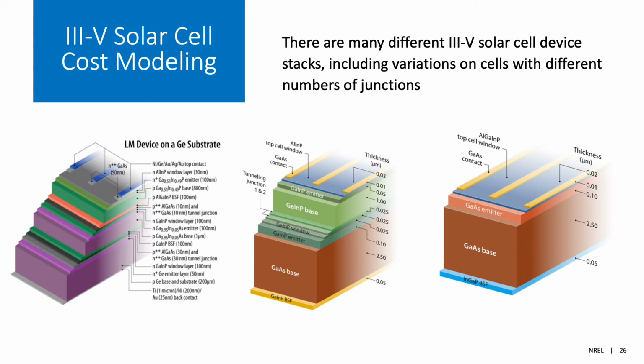So now we'll take a look at III-V solar cell cost modeling. There are many different III-V solar cell device stacks as well, including variations on cells with different numbers of junctions, as well as just having many different cells with single junction technology, dual junction, or 3+ junctions. What I'm showing here is the reference device stacks that we use for a 3-junction device, which is a lattice-matched device on a germanium substrate.